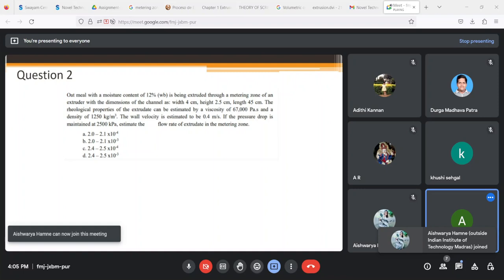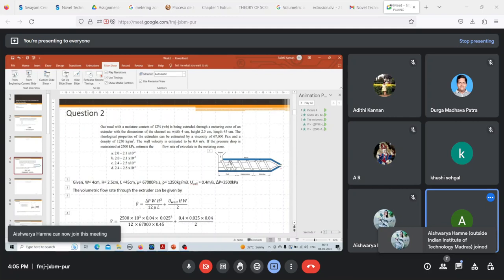So an extrusion process is when you want to get a desired shape of your food product. Like, say, how you have pastas of different shapes and sizes, those all come with a specific shape. So this is done by a process known as extrusion, where you feed in the dough or your raw material, and because of high pressure and temperature it will get extended, the shape will change, and at the end of the process there will be something known as a die, or a kind of a hole, that will determine the shape of the food that you are extruding.